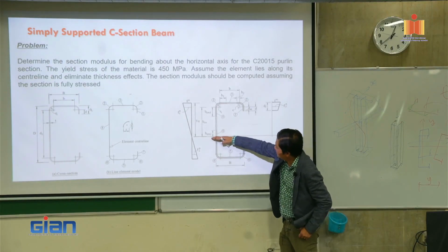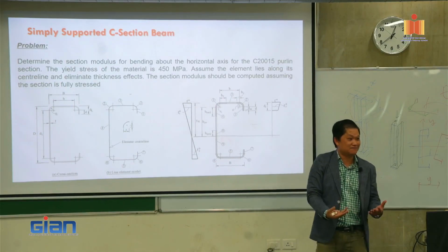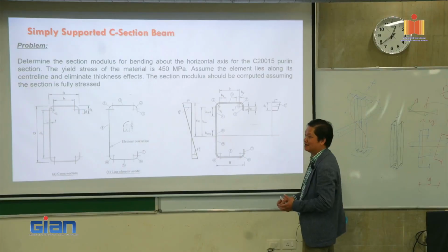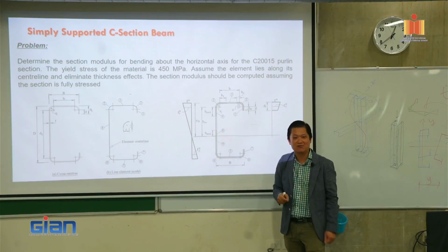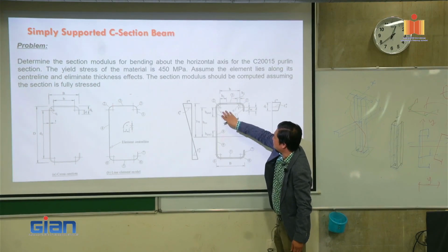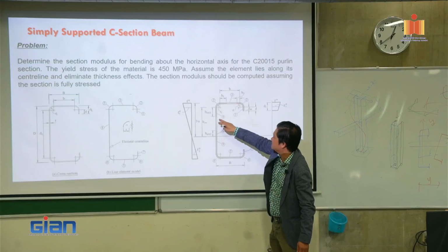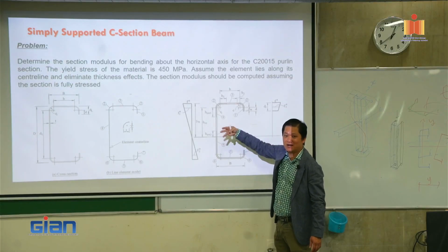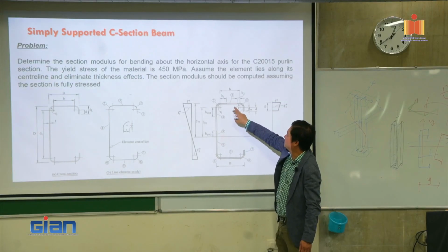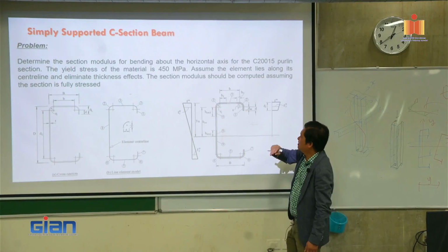And whatever element on the bottom here is in tension. So it means it's fully effective, nothing to do with buckling, right? Buckling is when we talk about compression. So from the neutral axis up to here, that's the problem maker, right? Because in here we need to remove some useless area where it's buckled, and then we calculate. That's how we're gonna do it. Right.